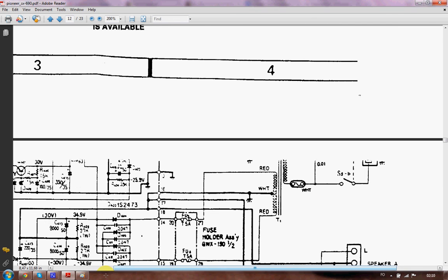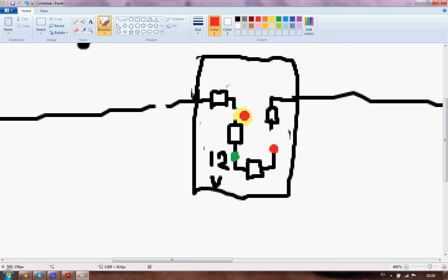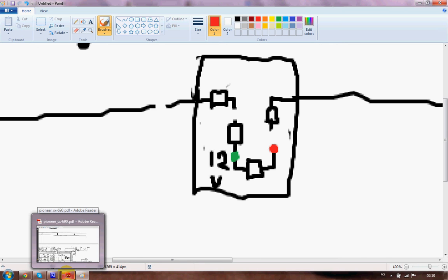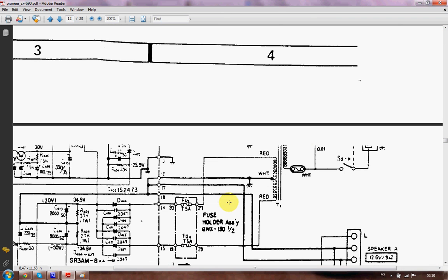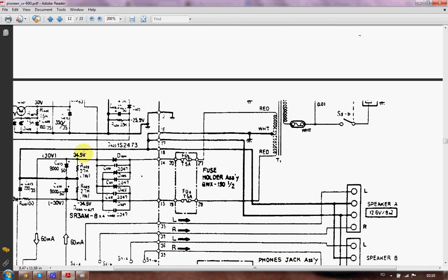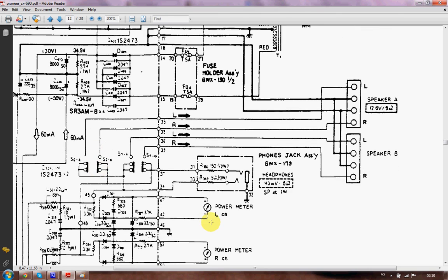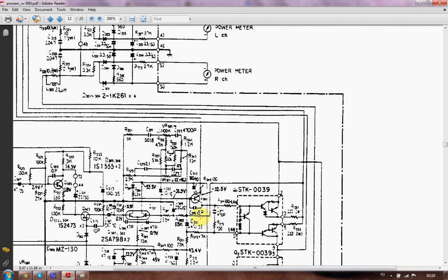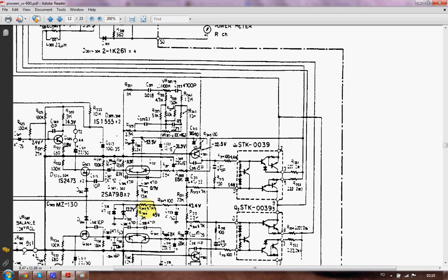So as I explained here, think about fluid, think even about water when regarding voltage in relation to current and brakes and how you should search for it. Try to use the given voltages in relation to ground. Search wherever you can for given voltages and look for signals. Do we have signals? Do we remain signals? Where do they disappear? Where do we lose the input?